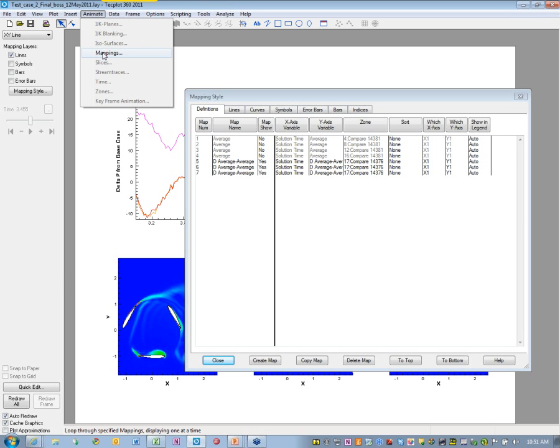Now it requires a substantial amount of memory to do that. In my case, it was 48 gigabytes. On a 64-bit Windows machine with 48 gigabytes, I can load a billion cell case. So that'll give you an idea of requirements. 2 million is quite easy. And on my underpowered laptop, I can load about 50 to 100 million without too much problem.